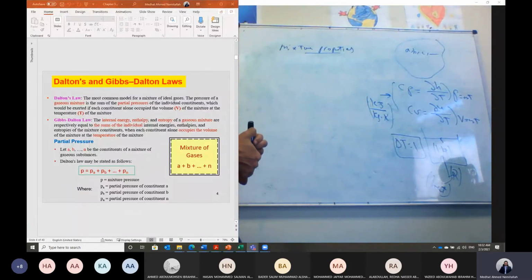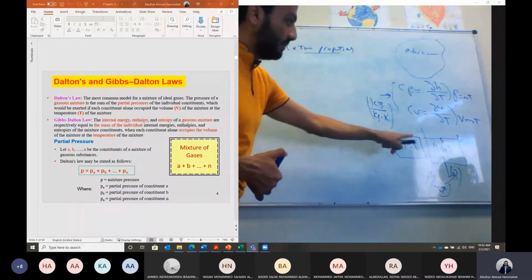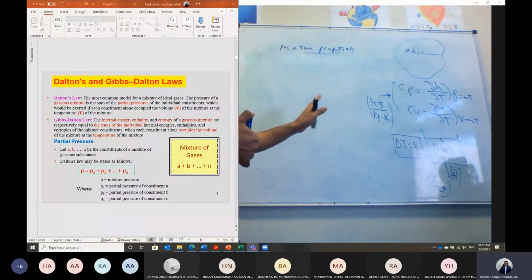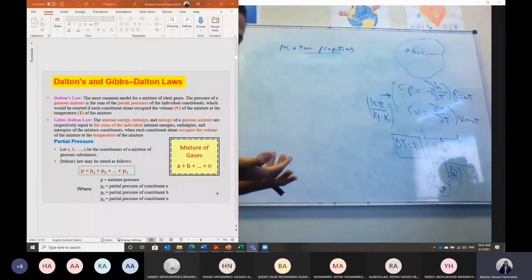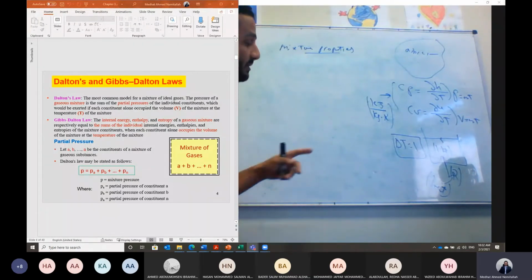This is the temperature difference. It is the amount of heat added per kilogram of a substance to have a temperature rise of 1 Kelvin. That means it gives us an indication about the energy storage capacity of a given substance: how much energy this substance can absorb for a given temperature rise.